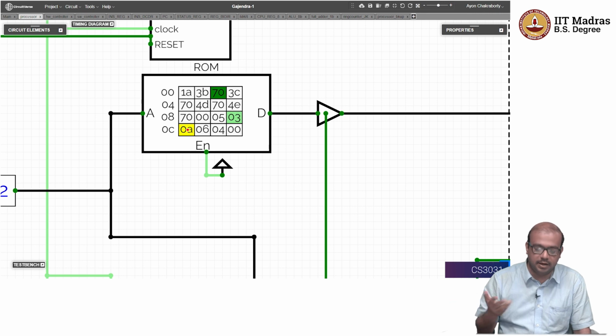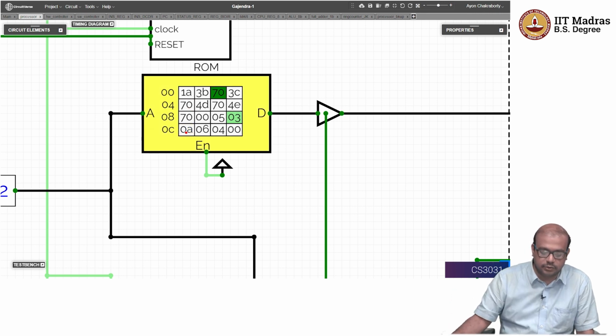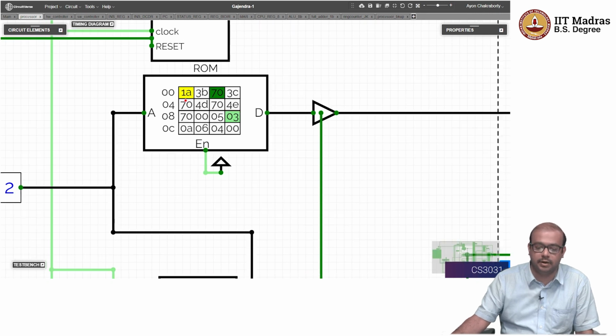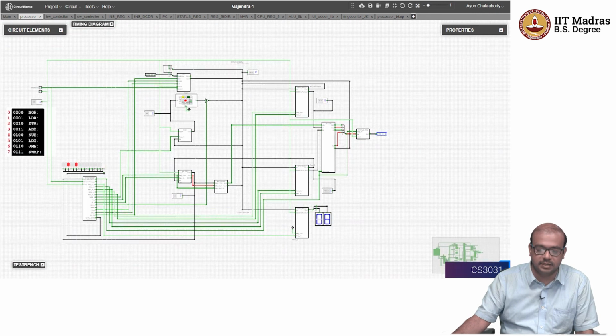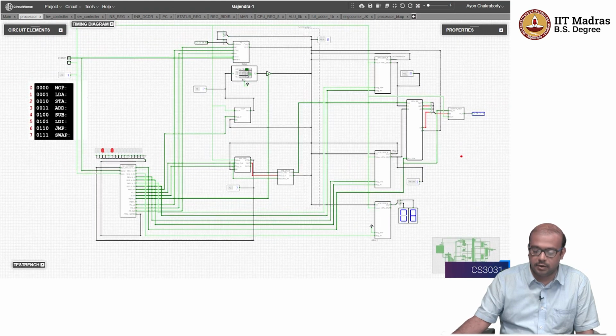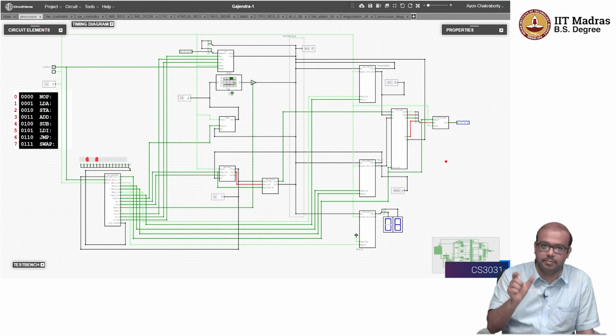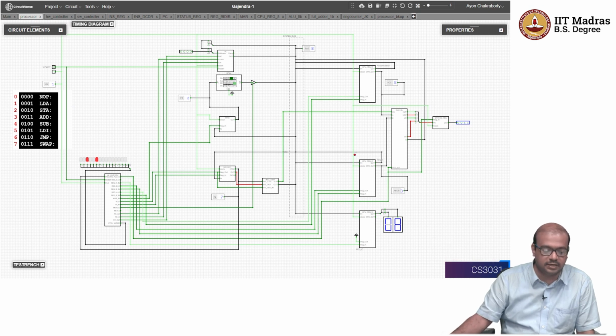This basically becomes 18. So after you execute 3C, followed by 70, the accumulator is going to contain the value decimal 18, or it is going to display the value 12, because it is hexadecimal. What can we do? We have to display that in hexadecimal form. We are doing this bit by bit, like 4 bits converted to a hexadecimal value. So let us execute that, right? I put one more clock pulse. I'll be skipping these clock pulses very quickly.